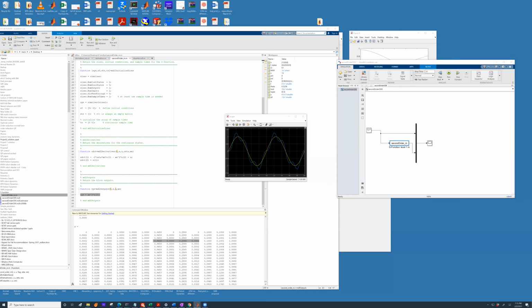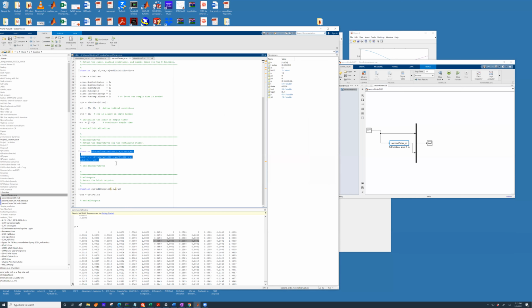Now, to answer Zubir's question, in this particular case, we used a function that was defined inside the Matlab environment. So you may say using an S function is sort of overkill. I can just use an interpreted Matlab function. That's totally fine. But the power of the S function is, if you have C code, you cannot use an interpreted Matlab function to run the C code inside the Simulink environment. With an S function, you can actually take the C code or maybe Fortran code and run it.